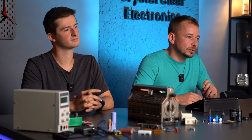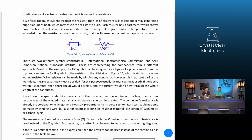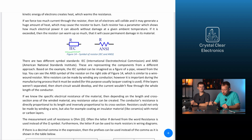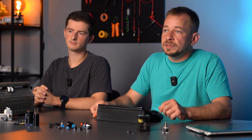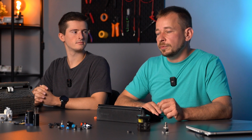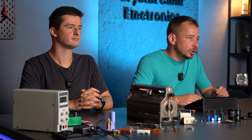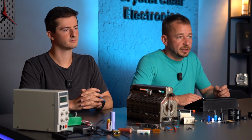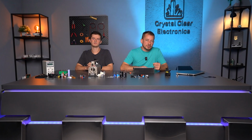material. Based on the example, the IEC symbol can be imagined as a figure of a pipe viewed from the top. You can see the ANSI symbol of the resistor on the right side of figure 14, which is similar to a wire-wound resistor and can be made by winding any insulated wire. But how? If we know the specific electrical resistance of the material, then, depending on the length and cross-sectional area of the wound material, any resistance value can be created. The conductor's resistance is directly proportional to its length and inversely proportional to its cross-section.